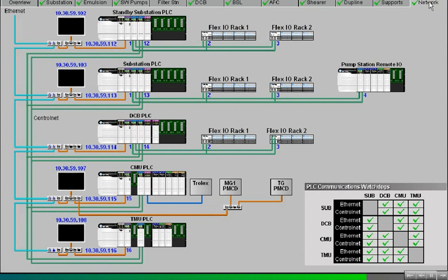The last tab in the Longwall system is the network page. This page provides a line diagram of the communication between Cytect and the PLC communications network. A comms watchdog is located in the right-hand bottom corner. A green tick shows all nodes of communication are healthy. A blank square indicates that either the Ethernet or ControlNet communication is down. Note, if both the Ethernet and ControlNet comms are down, a fault symbol will fill both squares.